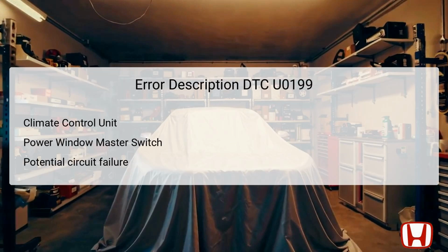DTC U0199 signifies a lost communication issue between the climate control unit and the power window master switch. The climate control unit is located in the driver's dashboard and is crucial for regulating the vehicle's climate settings. The power window master switch is typically located in the driver's door and controls all window operations.